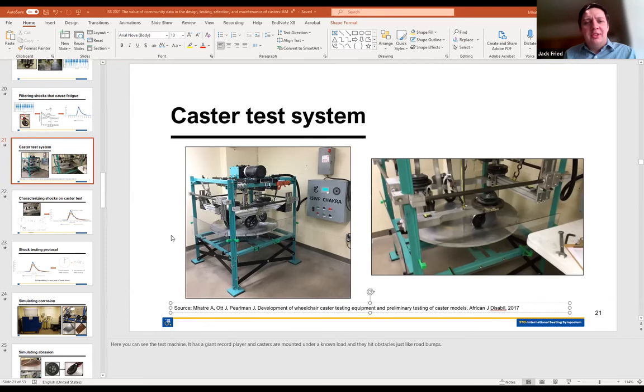And I think that relates to what Dr. Kuntz had asked, discussing the effects of user load on caster performance, and how it can inform wheelchair setup for frame design. Like Dr. Mhatre said, we are working to figure out how that changes across the different wheelchair types and what that looks like. So that's another change we can make to hone in those values. The caster standard asks the manufacturer to specify the load on the caster. For us, when we are doing this testing study or research studies, we are applying a standard load of 30 pounds on top of this caster.